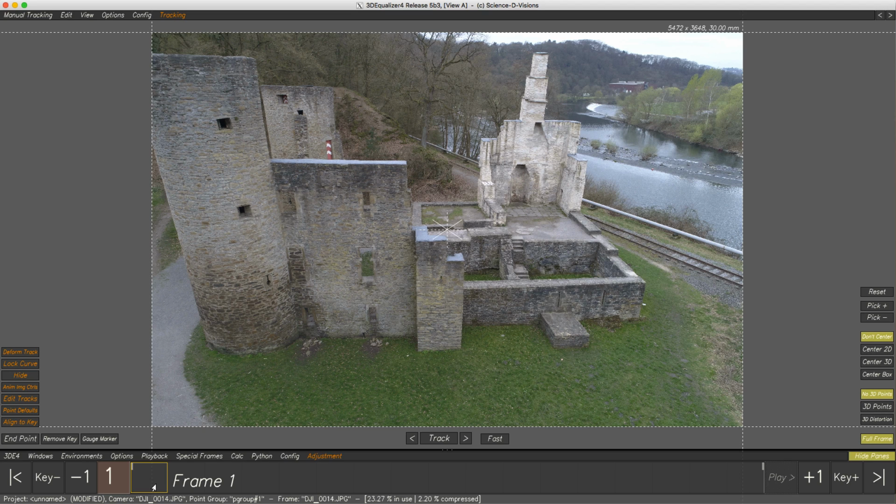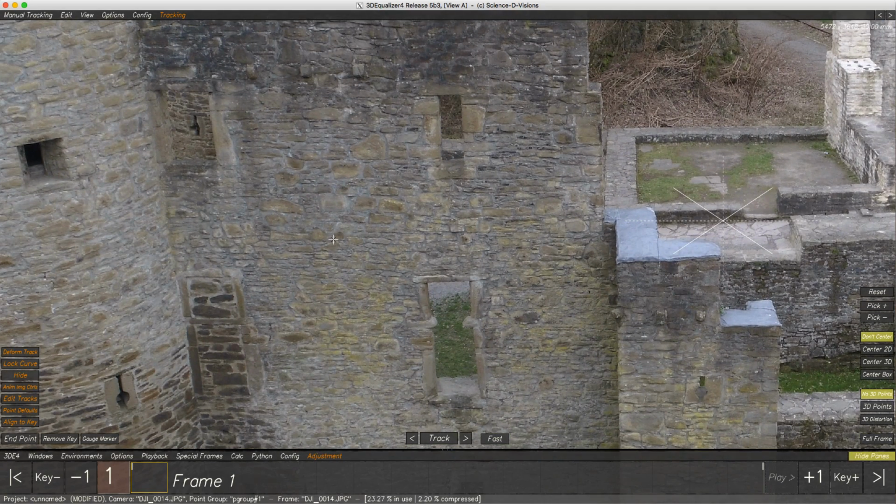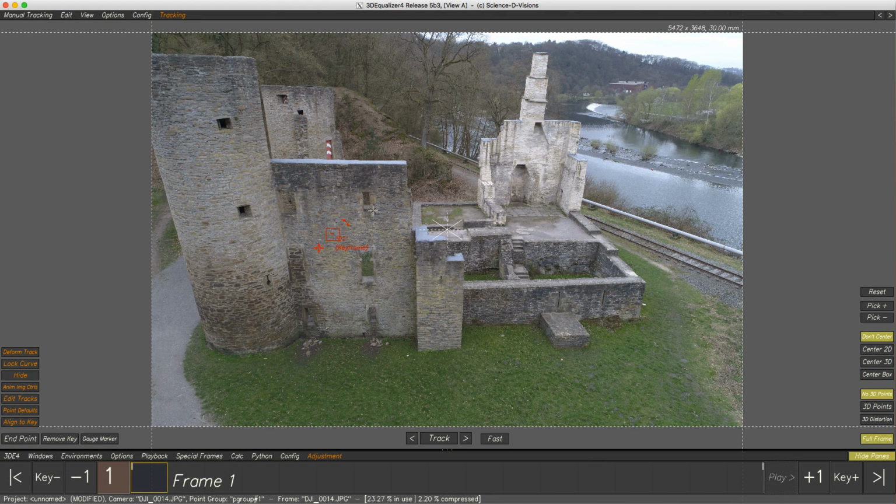So easy, it's the same as manual tracking. Simply control-click on a feature, and here we go. A tracking point was created in the current camera. Of course, it behaves identically to a tracking point within the sequence. Just the outer search box used in sequence tracking is obsolete here, since the defined pattern will be searched within the entire image. To track this feature, click on button Track.